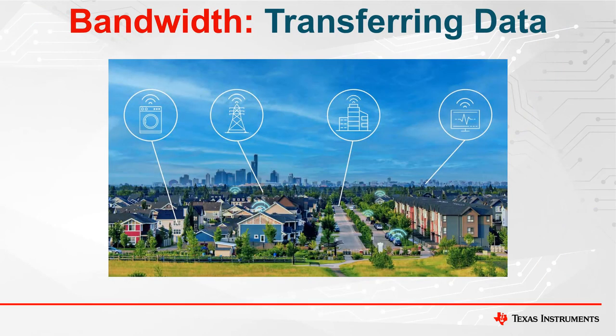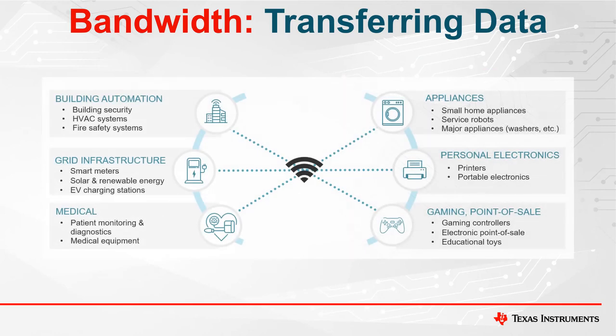The required bandwidth is a major consideration when choosing the wireless technology. An IoT sensor or accessory typically requires very low bandwidth, below 10 kilobits per second, and is idle most of the time. A smart grid, including smart meters, EV chargers, etc., only requires a few kilobits per minute, a very low data rate, while a compressed video stream may require a couple of megabits per second. All of these technologies support a periodic log dump or over-the-air update, which is efficient and user-friendly.